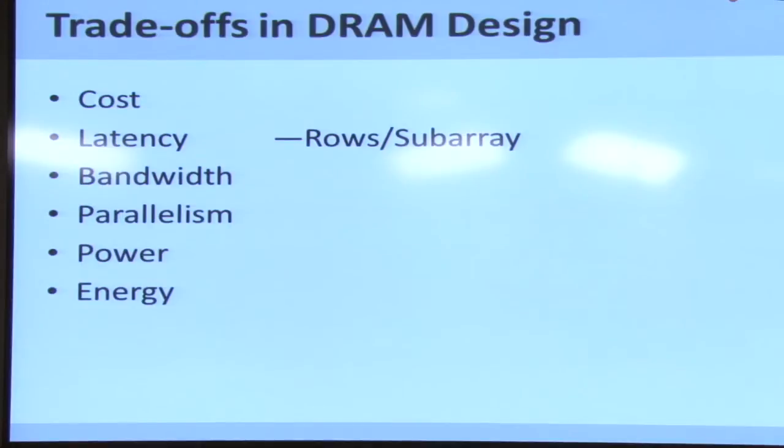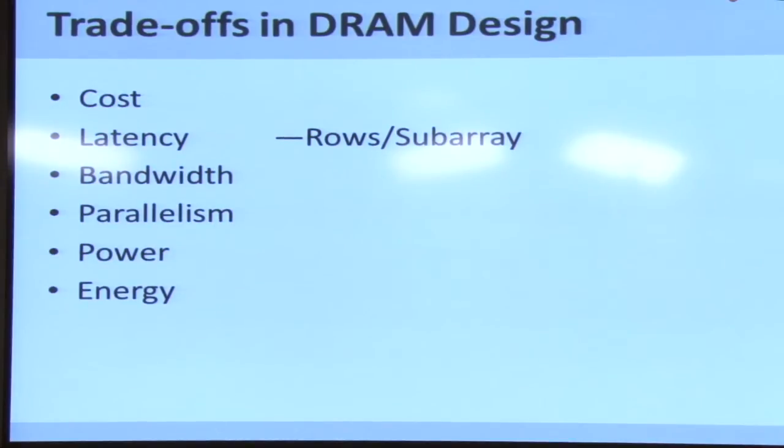Still, I have 64 bits of data fetched into my bank I/O logic, but I'm just sending 8 bits at a time, and each half cycle 8 bits are sent out, which means I'm spending 4 cycles sending out the 64 bits of data that I got. What benefit does this give? Why do you think I would only send 8 bits per half cycle?